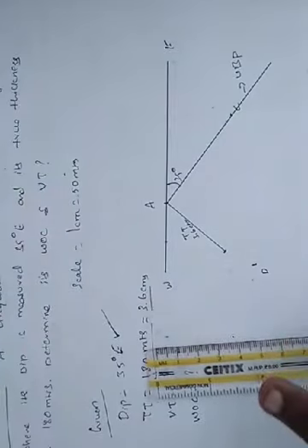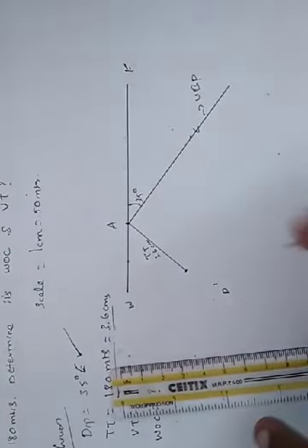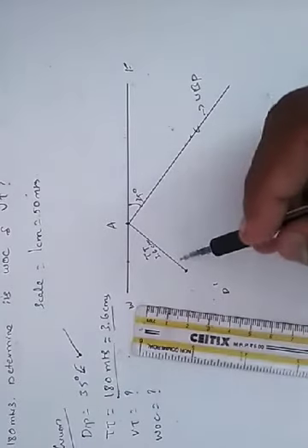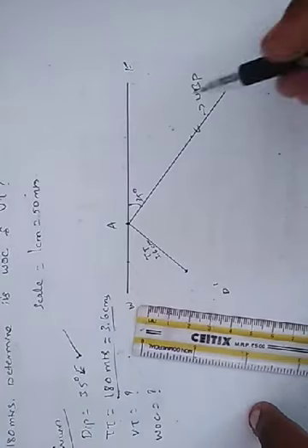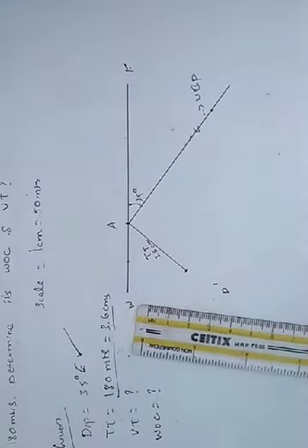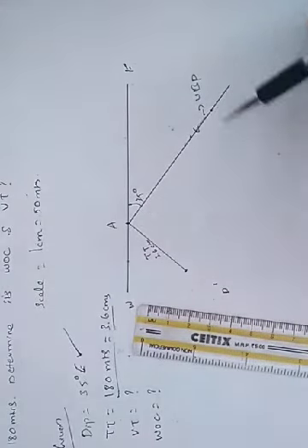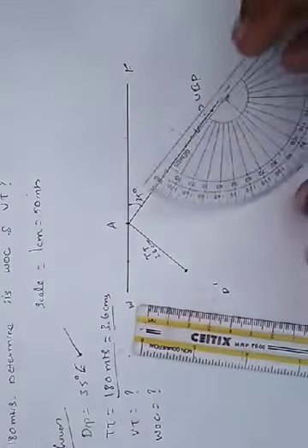So now to get the lower bedding plane, I will use the same line at some other point in this bedding plane. I will mark one more point on this line. I am using this point to draw a parallel line of upper bedding plane to get the lower bedding plane.